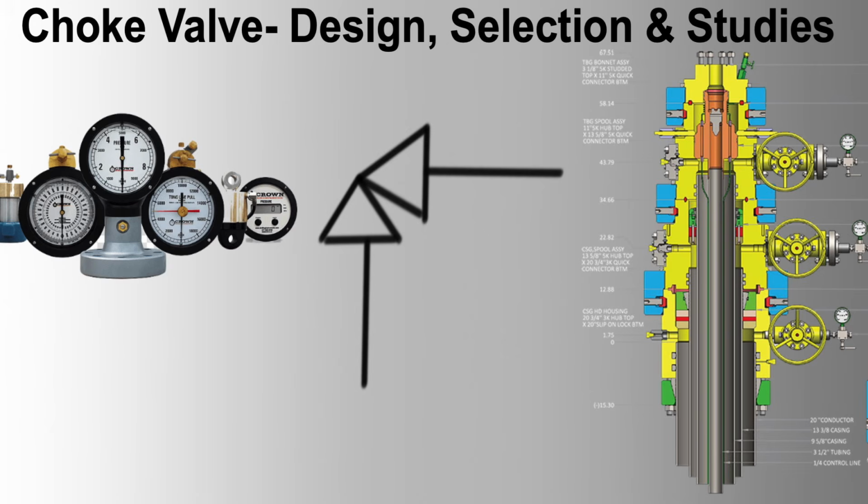7. Cage choke valves. Example, used in high-pressure gas lift operations to control gas injection rates. Advantages: noise reduction, designed to reduce noise and vibration, ideal for high-pressure gas applications. Cavitation control, effective at controlling cavitation and erosion. Precision, provides precise flow control with minimal wear and tear.